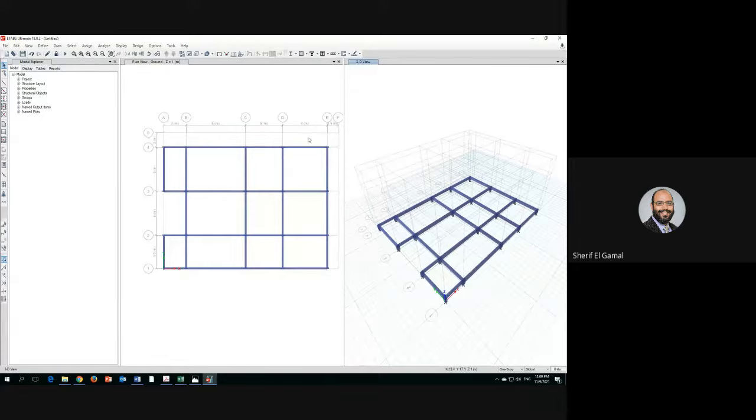If you want to repeat the beams only, we don't have a slab on the ground here. There's no slab, so these will be the plinth beams at the ground floor level. Why do we use the plinth beams? To build the walls at the ground floor on this. So these beams will carry only the load from the walls because you have walls here.